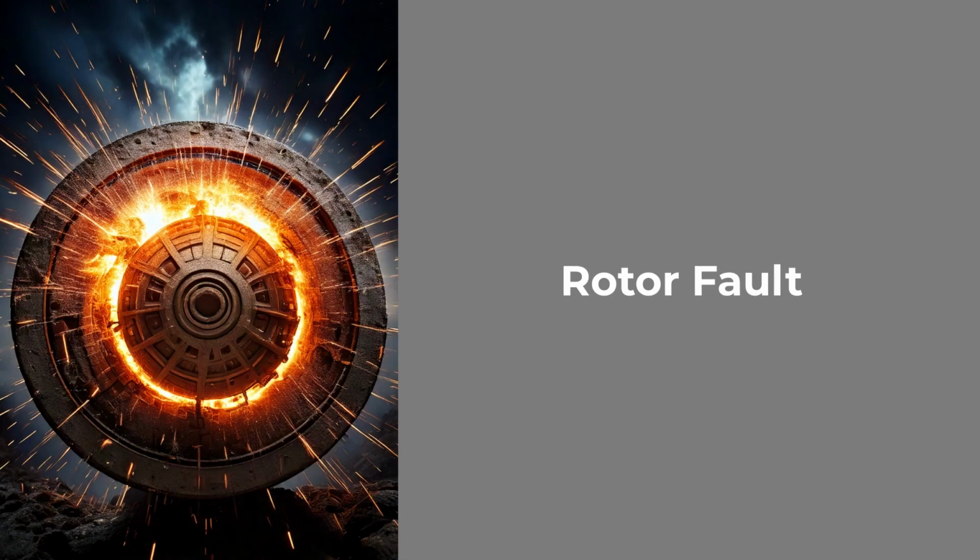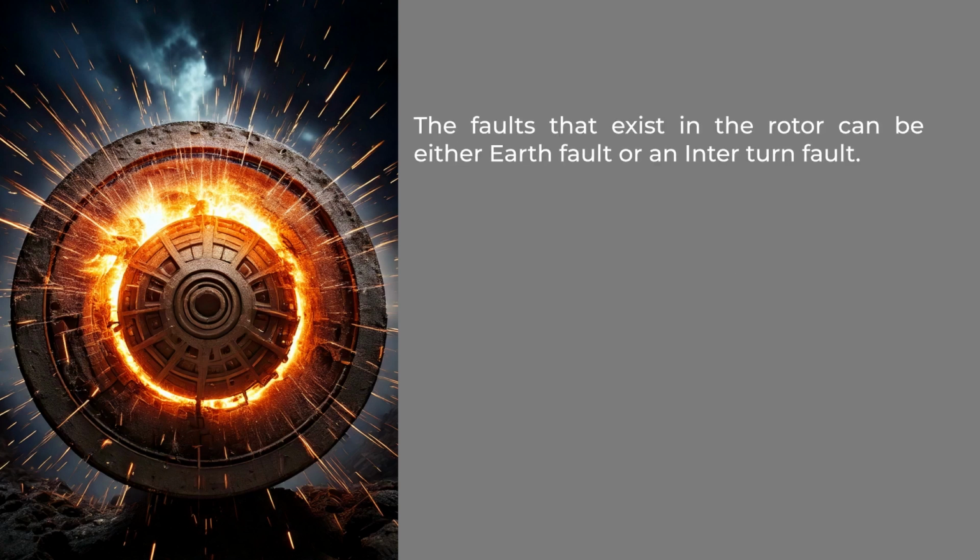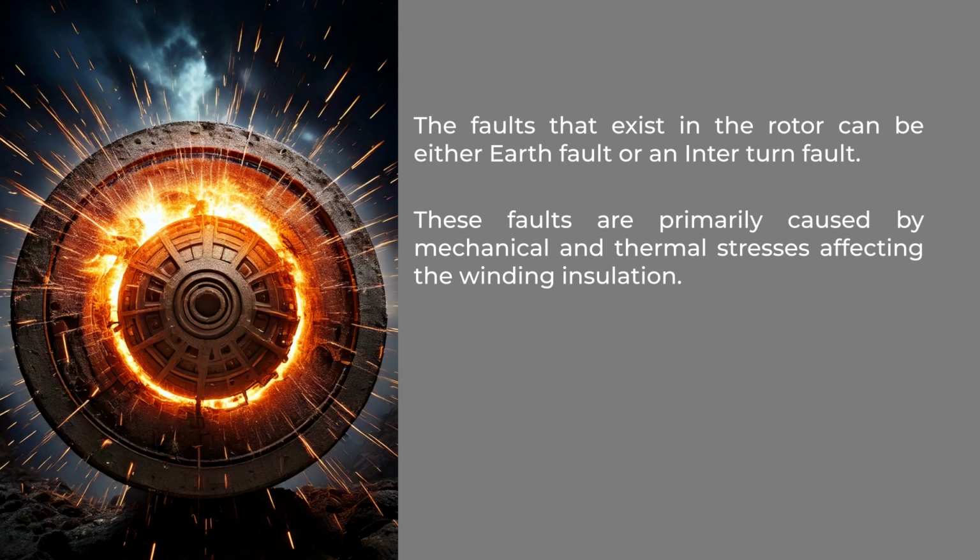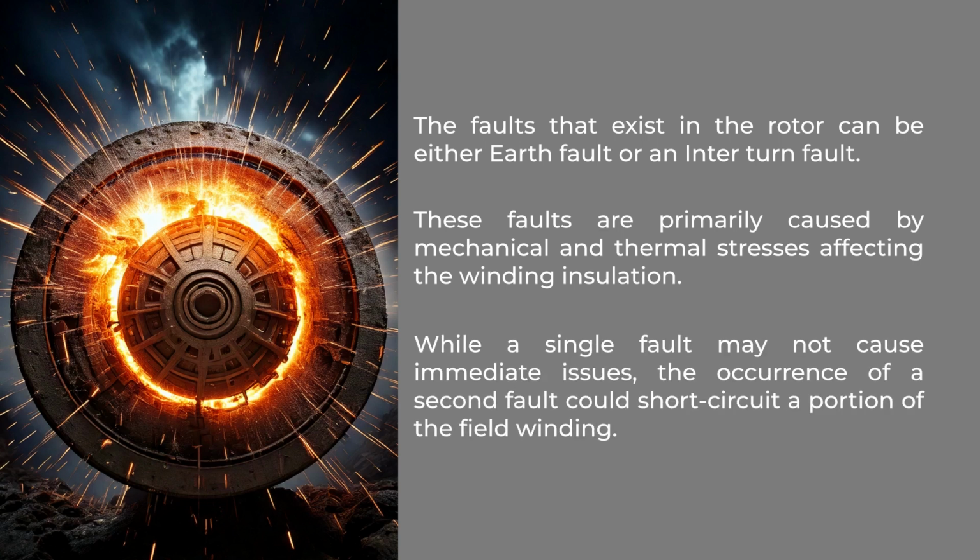So, this is all about the stator fault protection technique, where we basically use differential protection and, for each condition, we modify that differential protection. Next, we move toward the rotor fault protection technique. Rotor faults can be categorized as either earth fault or interturn fault. These faults are primarily caused by the mechanical and thermal stresses affecting the winding insulation.